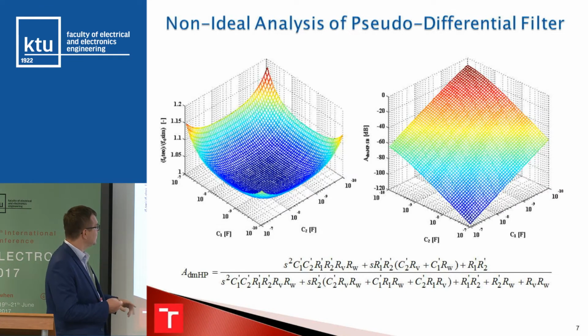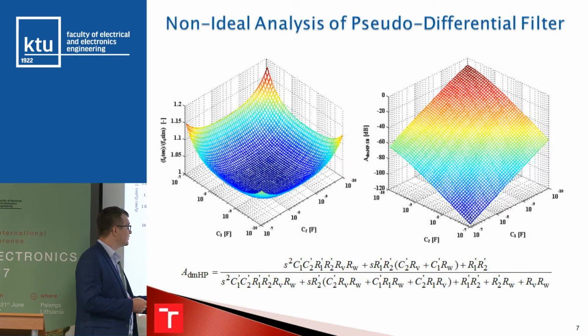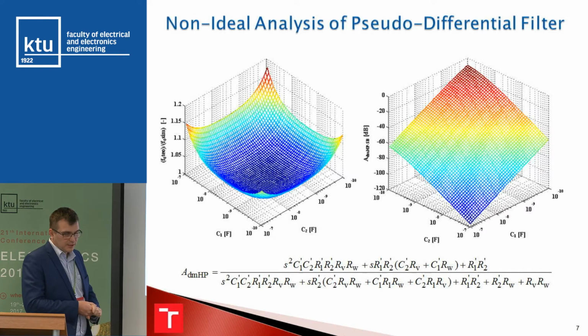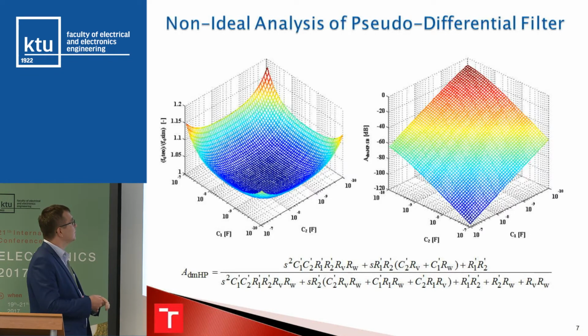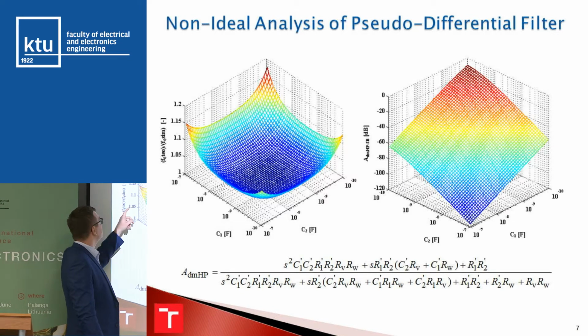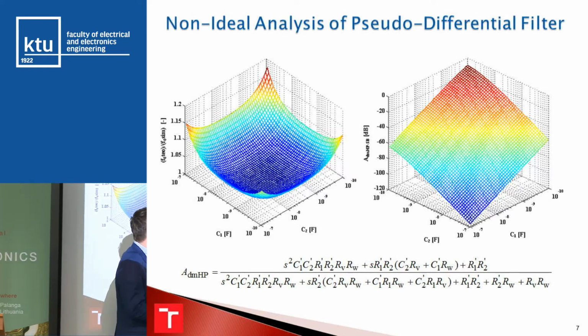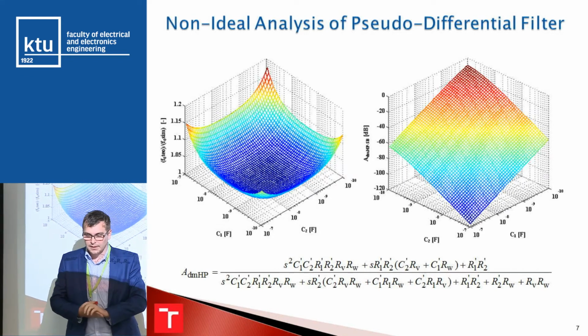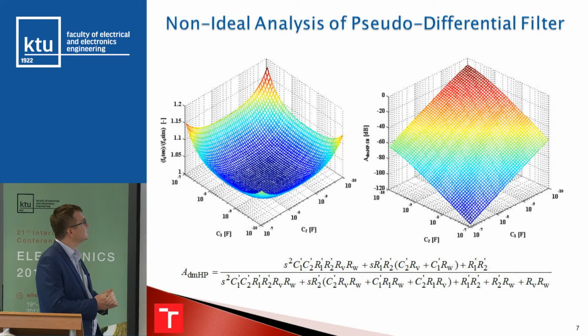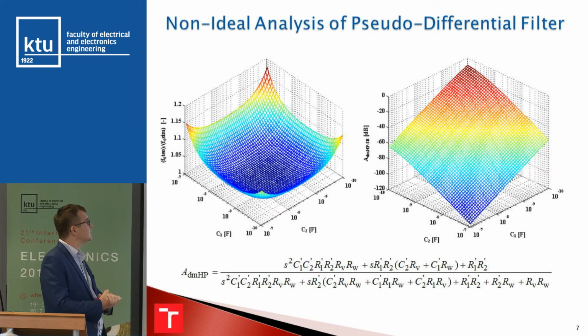And here we see how the transfer function of the high-pass filter in this example changes the main parameters that we are looking for. So for example, here is the change of the theoretical and true center frequency, and here it's visible the maximum attenuation in the stop band of this high-pass filter, so at lower frequencies than the center frequency.